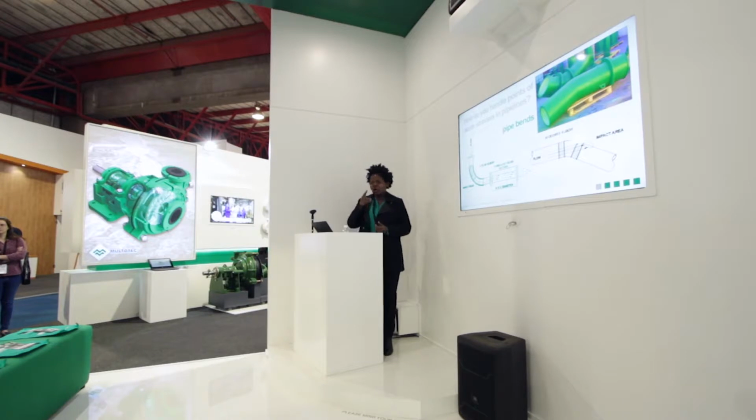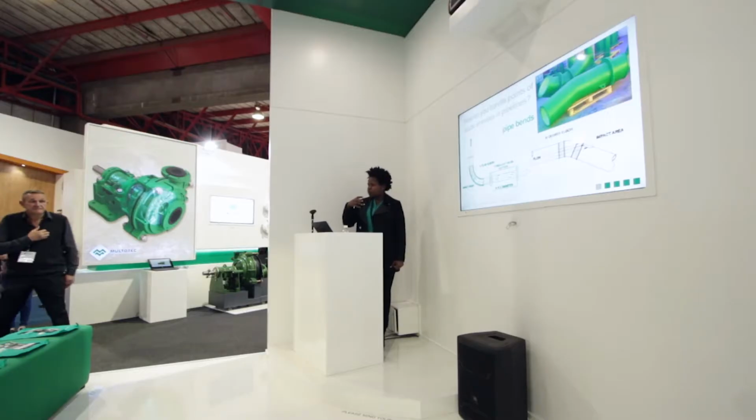Also, on that elbow, when you have material that has to take a turn, the impact angle, like the angle at which it hits the pipe, makes the area that's encircled there the impact area, and it becomes a high stress area. So you want to make sure that the type of lining that you have in that area can accommodate the impact that you're going to have.